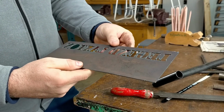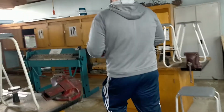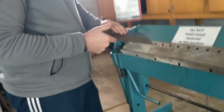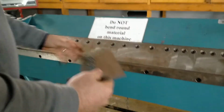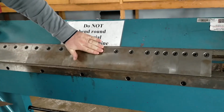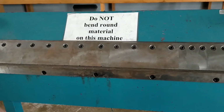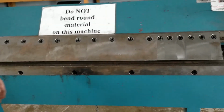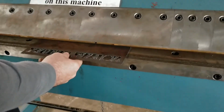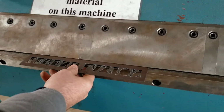But really quickly, what we might do is walk over to the pan brake. So if you come over here, we've got the pan brake, and I'm just going to show you guys really quickly how I'd fold this up. You see here, it's actually got the perfect angle on the teeth already to have this folded too. So on the foot plate down the bottom here, I open that up, fit this in under the teeth, and line this up reasonably close.